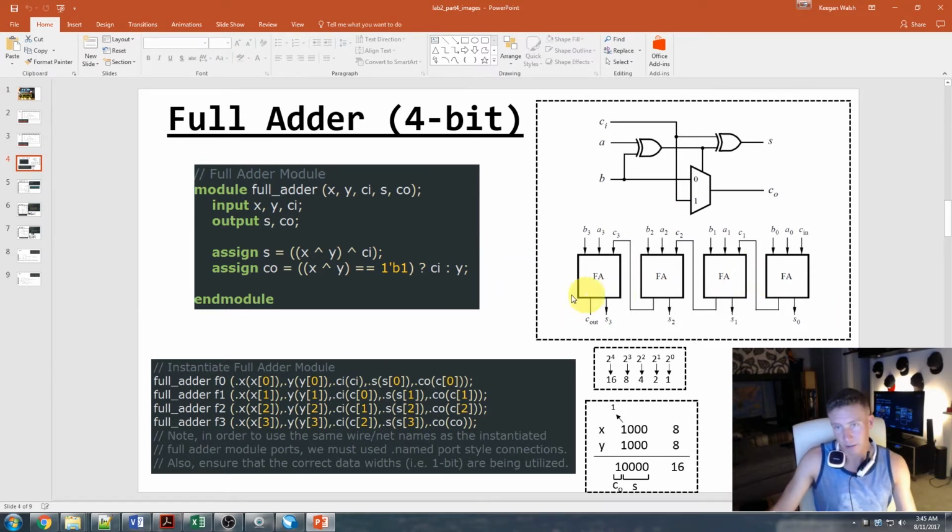Okay, one more last thing to touch on that's really important for this lab. When you add two 4-bit numbers, you need to have that carry out to represent that 5th bit, that more significant number. As an example, pretend that we want to add 8 and 8 together. We know that result is going to be 16, and as you can see, the sum is actually all zeros. So how do we manage the remaining sum when we have a 5th bit in there, when our carry out bit is a 1, for example? Just keep that in the back of your mind about that 5th bit.